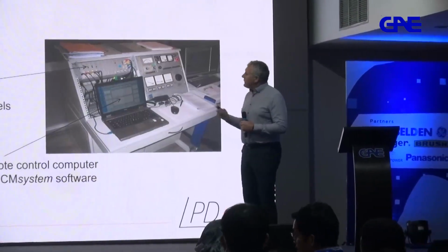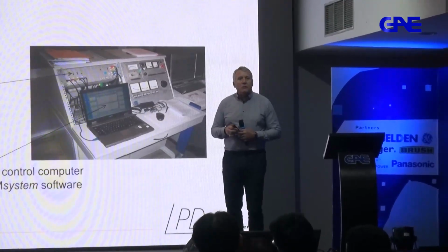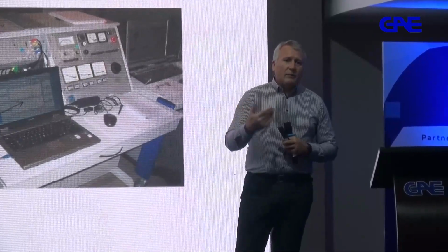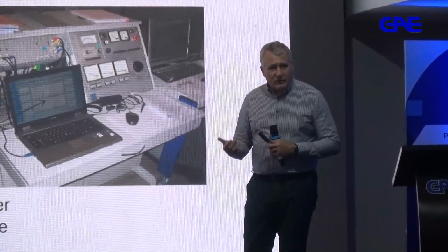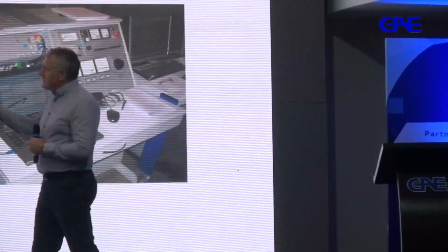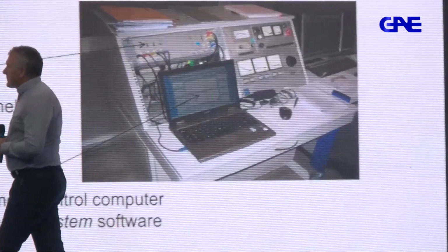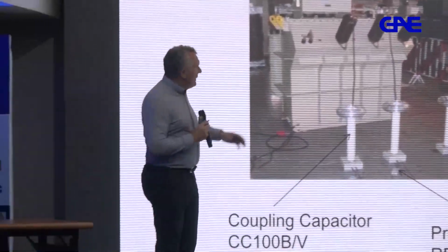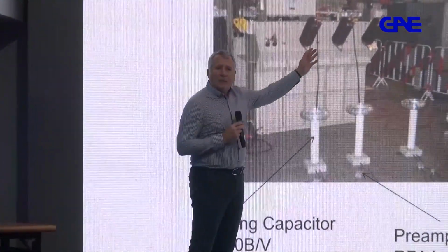Equally, when you have a distribution transformer, the same norms apply. The same quality needs to be required from the manufacturer. And you should get these test reports, the partial discharge test reports, because they need to perform these tests. And you should ask your colleagues manufacturing such transformers for you that they provide you with these test results. Okay? How these tests are done is slightly different, because in the case of a distribution transformer, the bushings of a distribution transformer do not have that capacitive coupling.